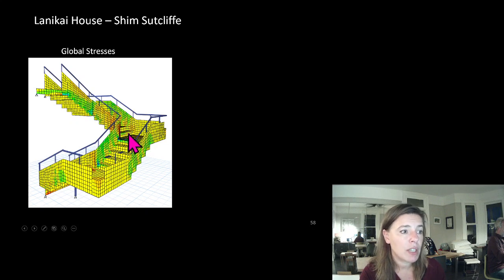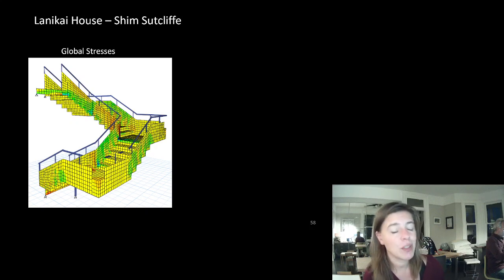So we want to make sure any of our factored stresses are less than 0.9 of 345. So 0.9 times 345, we've got 310. Actually, it was plate steel, so 0.9 times 350. So 315. We want our internal stresses to be less than 315 MPa.